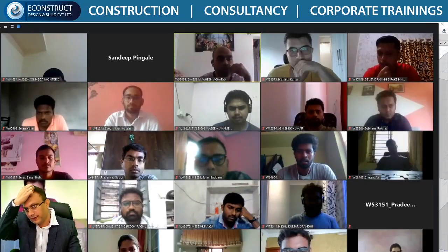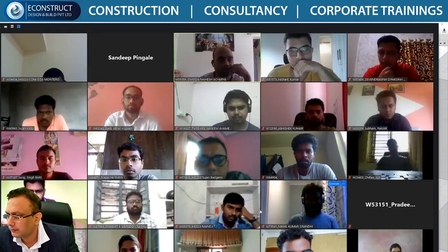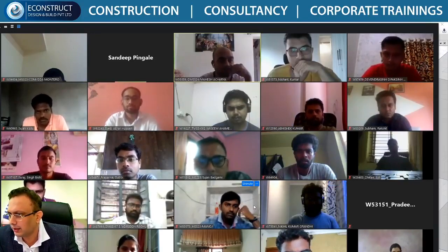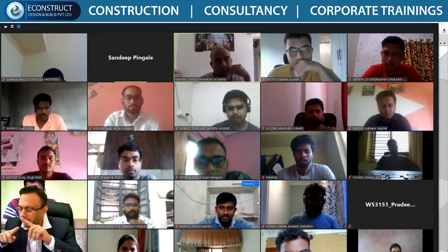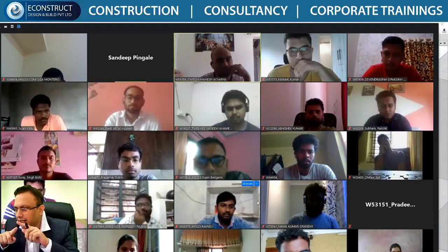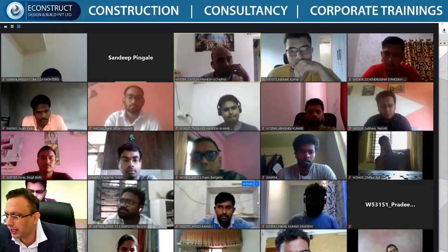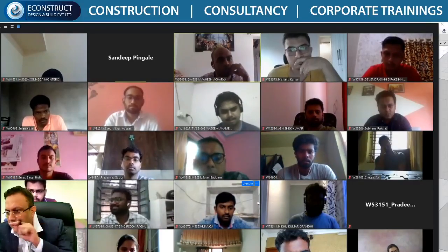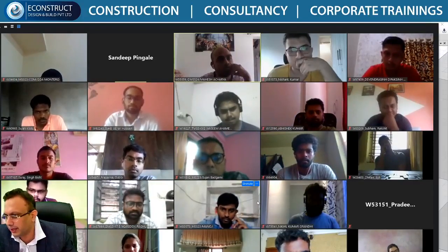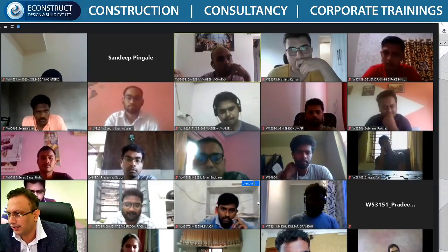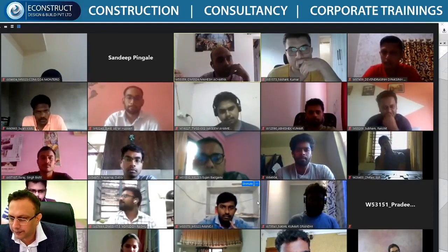Any other question? Anybody? Sir, yesterday's process and assignment, in that case, to give releases for truss, releases to every member. Then you give the releases. But after giving the releases, you need to give the tension and compression limits also. If you give the tension limit as 0, it will become a compression element. But when we run the analysis, it gives instability.